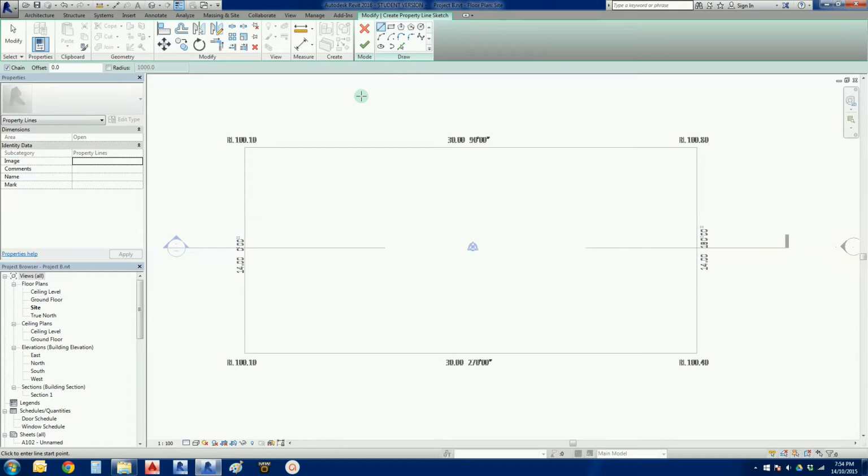But today I want to show you another nifty little tool called the Pick Lines tool. So it's this one here, a little arrow overlaying a line, and it literally does what it says: it picks lines. If I click on that, Revit will look for lines, arcs, pre-existing information. So now all I need to do, there we go, hover over a line, it's found something, left click, drop, and it adapts itself perfectly to the lines and arcs and curves that are already there.